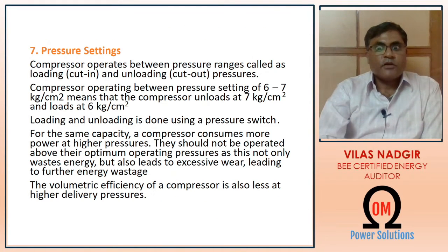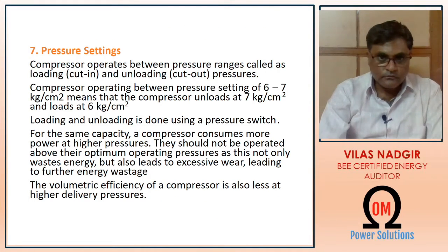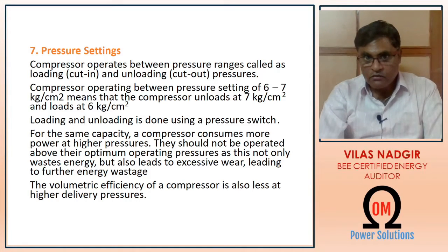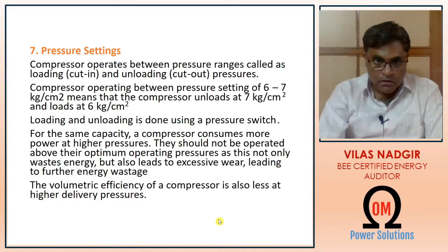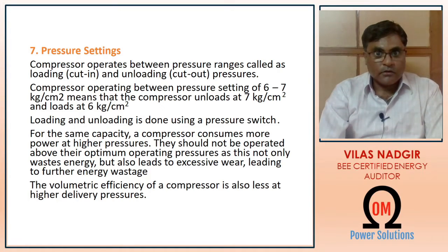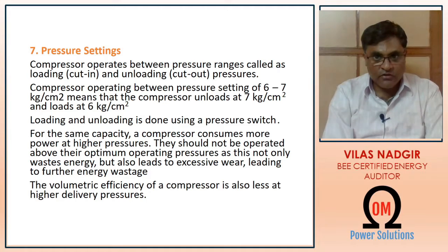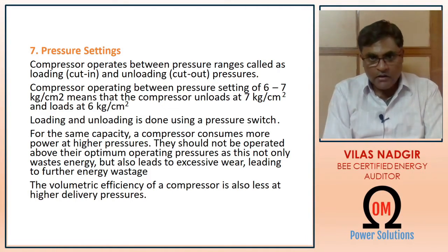Pressure settings. Compressors should not be made to operate above their unload pressure settings. Usually all the compressors are operated between two pressure settings known as cut-in pressure and cut-out pressure. Cut-in pressure is also known as loading pressure and cut-out pressure is also known as unloading pressure.